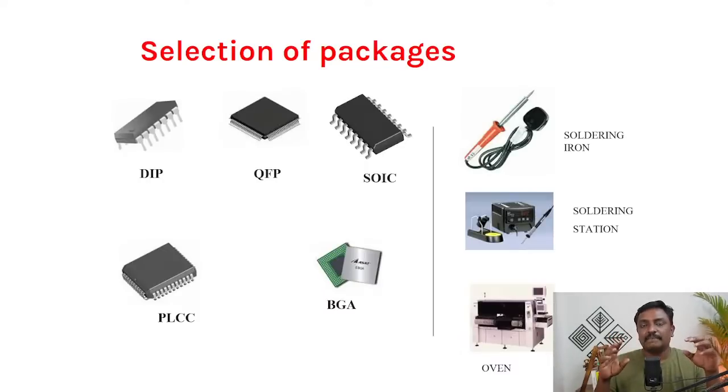The reason is that when you have a larger pin count, it is not viable to have it in a DIP package or a quad flat package. Quad flat package can have 204 pins or 176 pins. That's the maximum pins available in the quad flat package. When the pin count is more than 250 or 300, it is available only in BGA, ball grid arrays. Most of your mobile phones have this package. The ICs in mobile phones have this BGA package, and the Pentium 4 processor, a general purpose processor, will have this BGA package.